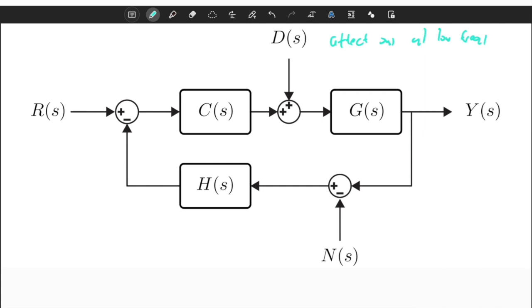Of course, a couple of hertz depends on the system, but basically, if the bandwidth of your closed-loop system is F, it generally affects your system in the order of F divided by 10 or something like that. Of course, it depends on the system. So this disturbance is generally a low frequency behavior. The reference signal is also a low frequency behavior. We generally try to track a step, ramp, or signals that are smooth and nice. They are not stochastic and noisy. It's technically stupid to track a stochastic or noisy high frequency reference signal.